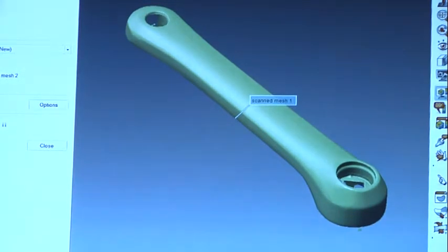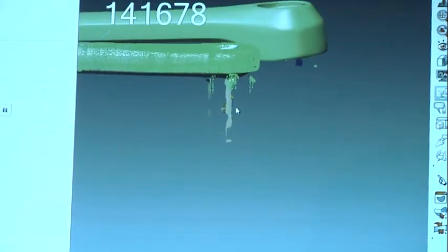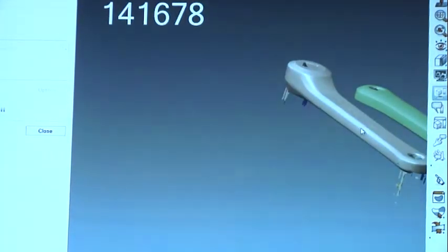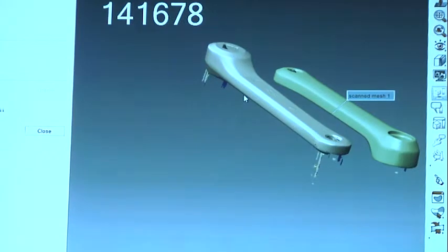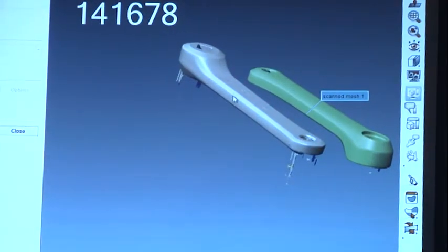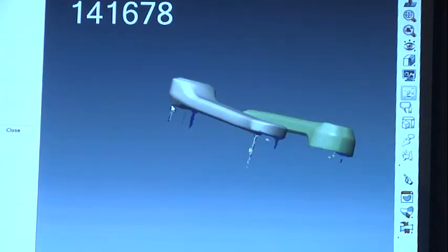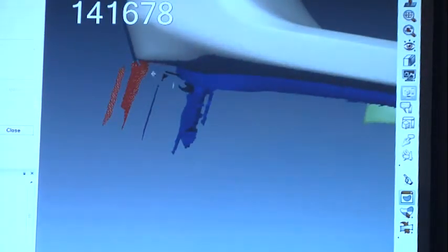So I'll click Start Scan, and we did speed up scanning here for the simulator in order to make it quick. But we did several scan passes to fully cover the bottom section of it. Now, in this case, you see I did scan some portions of the fixture. So at this point, I probably want to get rid of those, just to ignore them from the best fit, ignore them from the mesh algorithm or the mesh processing.